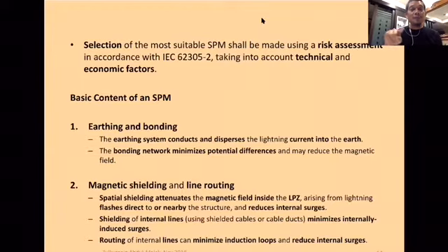So you not only put the boundary SPD, but the SPD itself has a class level, whether you put class 1 SPD, class 2 SPD, class 3 SPD, class 4 SPD. For example, if you put class 4, the risk is still high. So you want to reduce to an acceptable limit, you need to put class 1, for example. Then you're okay. Similarly with shielding.